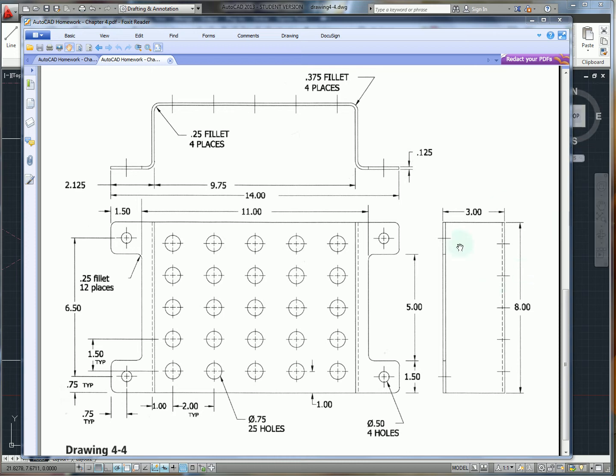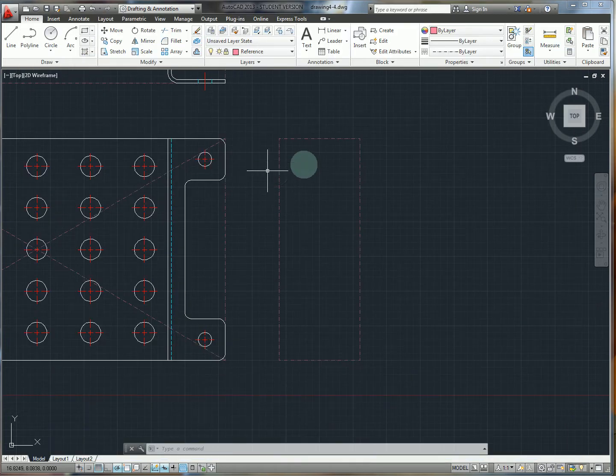So finally, we're going to look at the third view over here, and this is the side view based on our front view here. This would be considered the right side. And so here, it's actually the simplest of the three. We just have to propagate over a few of the pieces of geometry from this side. So I've started with our reference geometry here.